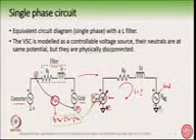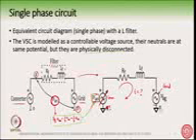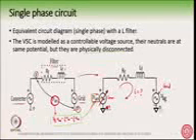So this concept must be very clearly understood. When you are in a single phase system, of course when you do the 3-phase system it will be clearer to you, but when you want to analyze the single phase model of the 3-phase VSC, then we make the model something like what I have shown on the right hand side, where you have the grid voltage on the right, and we have the RF and LF. This is the filter.